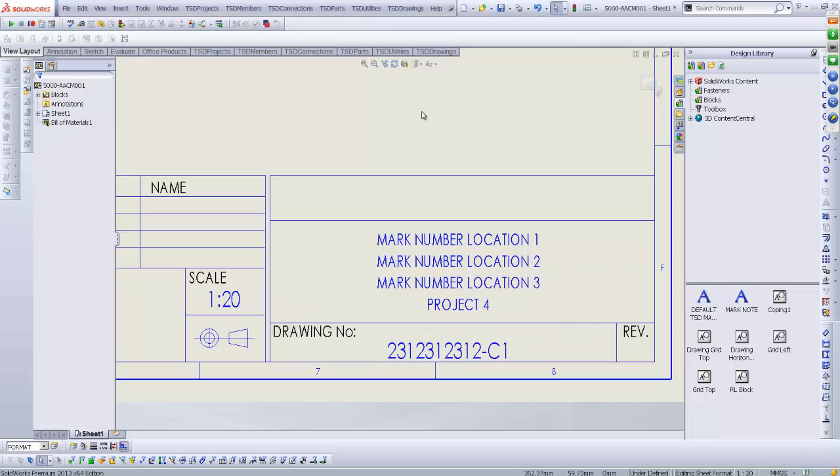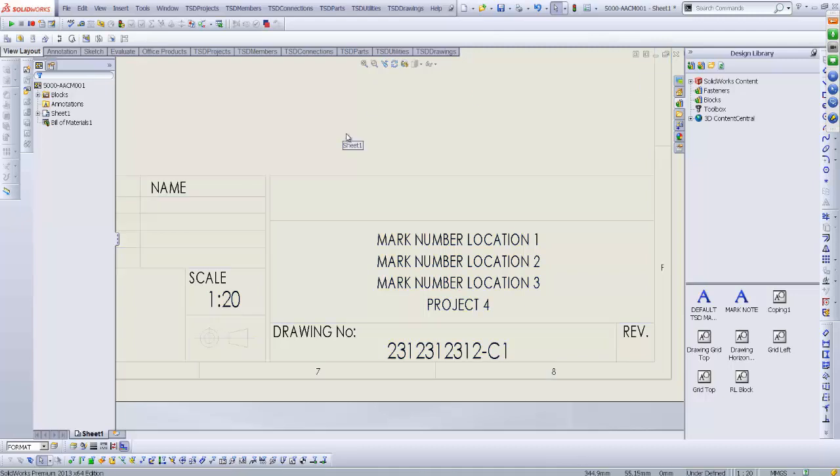Okay, so this is where you can add in your own information, and you can do this anywhere within your drawing sheet with any text. Okay, it links it to the custom property of that item. Now if there's nothing there, you get a blank. So however, you have to come back and then update the custom properties of the item.